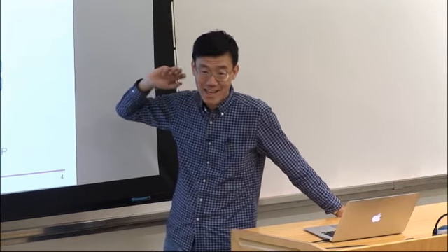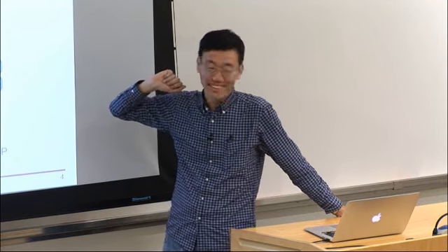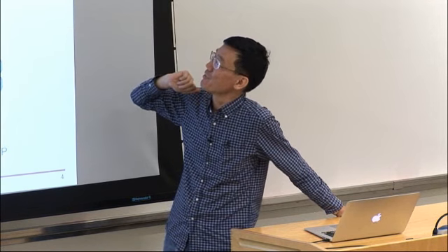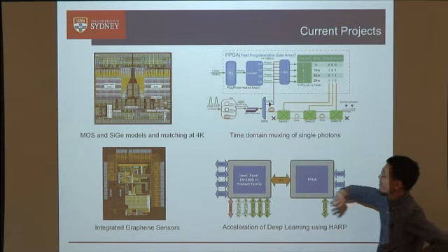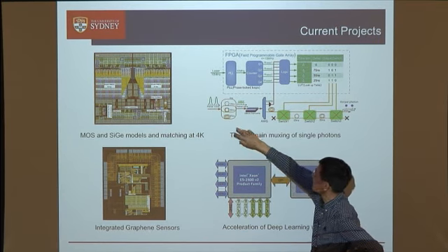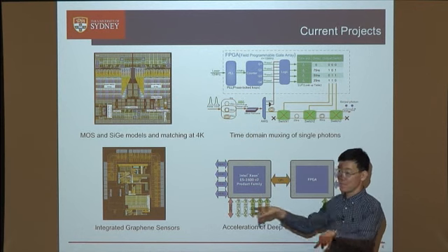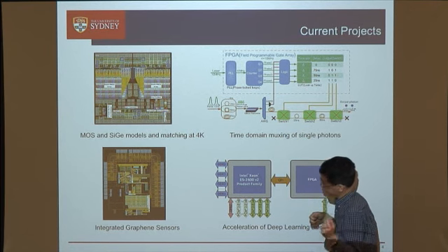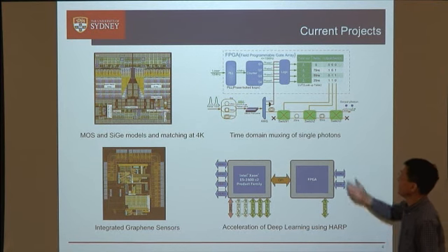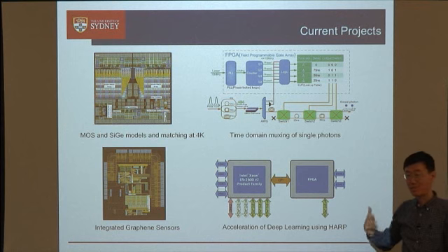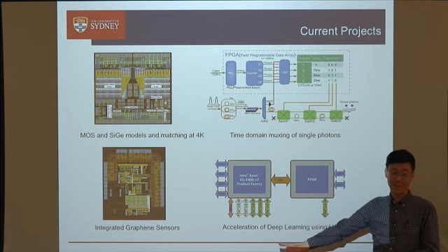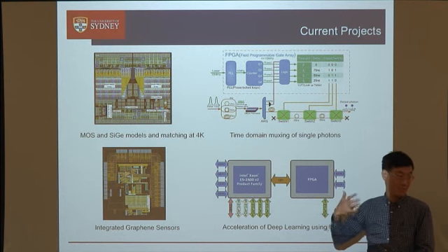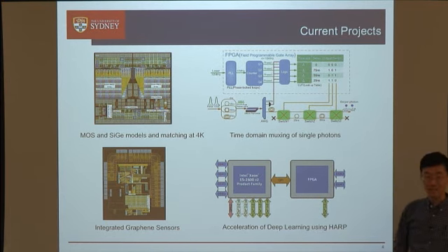So this is a photonic setup, and our contribution is including a few NAND gates, but they're very important because in this experiment, what you do is that you detect single photons which are generated in pairs, and when you detect one photon, then you can multiplex the other photon so that it always appears on phase one of a four-phase clock, and then you can increase the probability that the photons occur on that particular phase.